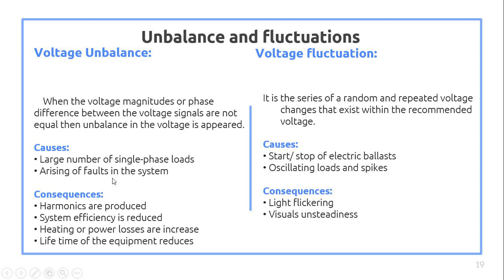The consequences of voltage unbalance are that harmonics are produced, system efficiency is reduced, heating or power losses are increased, and the lifetime of the equipment reduces.